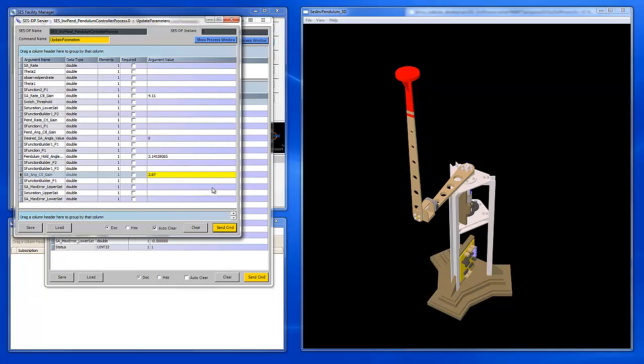All right, so that gives you the idea. Basically, because we've converted the MATLAB model to a distributed process, we can dynamically change any of these parameters on the fly while the system runs in hard real time. In this case, our controller plugin is driving a dynamic simulation of the pendulum hardware. However, the same procedure can be used when we move the controller plugin into the real-time environment and run it closed loop with the actual pendulum hardware. This is shown in Part 5 of this video series.